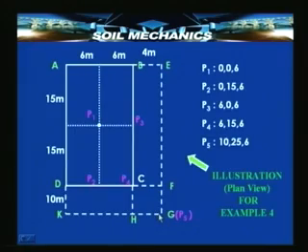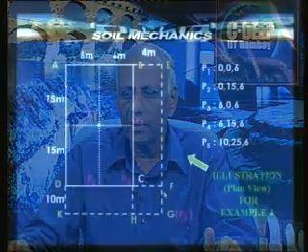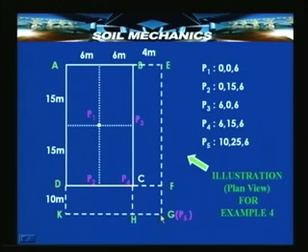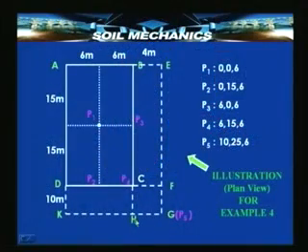So, now we need to subtract from this the stresses that we have obtained in addition because of considering a larger area. So, we take rectangle DFGK, which has a corner again above the point G, and therefore, this rectangle and its influence coefficient can be computed and the stress can be computed and subtracted from the stress that we obtain for the total area AEGK. Similarly, BEGH also can be considered to be a rectangle with a corner at G, and the influence coefficient for this and the stress corresponding to this can be computed and also subtracted.